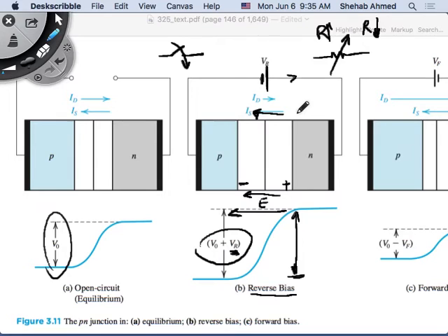Right? It's uncontrolled, meaning it's controlled by external circuits, not by the physics, due to an internal stimulus, for example. Right? So do we agree that we aided the barrier voltage, meaning we limited diffusion more? If you limit diffusion, you limit your majority carrier transfer, right? So what we're trying to avoid is to limit diffusion. You want to control diffusion.